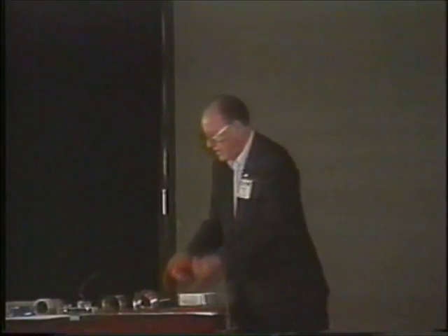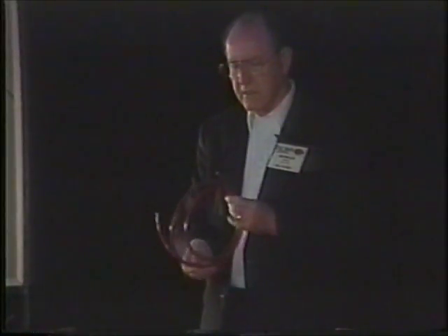Okay, if you want to get into amps and other sorts of things, then we have to start using larger wires. It's the flux lines, the magnetic flux lines, that are reacting with these particular coils and transferring the energy from one energy triangle to another. If you get into heavy amperage and that sort of thing, this is welding cable, and it comes in all sizes. This happens to be number 8 welding cable, and it will make a very nice high amperage type coil for your L2, and then you can use even larger cable or copper tubing for your L1 coil.